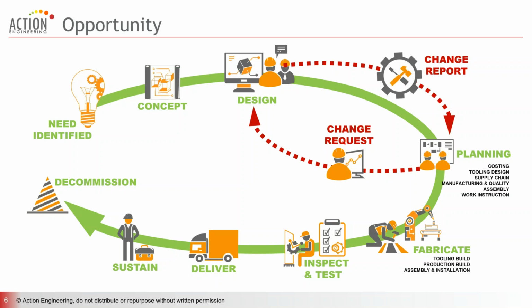So in a 2D drawing-based world, when we're relying on 2D drawings, I think everybody who has done the homework around MBD and has been introduced to MBD understands all the ambiguity around a 2D drawing, because it's a two-dimensional medium trying to describe and communicate something that we make in the real world, which is three dimensions. Right? So we do have to deal with a lot of that ambiguity, and geometric tolerancing is a three-dimensional language, which really removes a lot of that ambiguity, which is why there's such a synchronous relationship between model-based definition and geometric tolerancing.